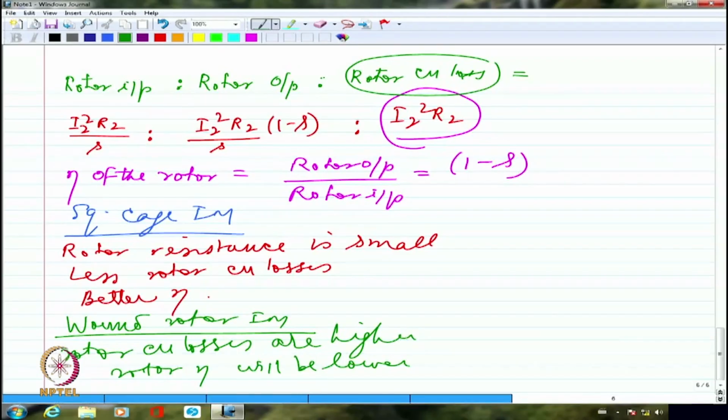See, I am giving 400 volts. Let's say it's a 50 hertz induction motor, 10 ampere of current. Root 3 multiplied by 400 multiplied by 10 multiplied by whatever is the power factor, let's say 0.8. That is the input. That is set in stone. I can't do anything. From there, already some I1 square R1 is gone. Some core losses are gone. Let's say those are some factors, maybe some X and Y. Now what is left over is root 3 multiplied by 400 multiplied by 10 multiplied by 0.8 minus this X minus Y. That is available as rotor input no matter what.